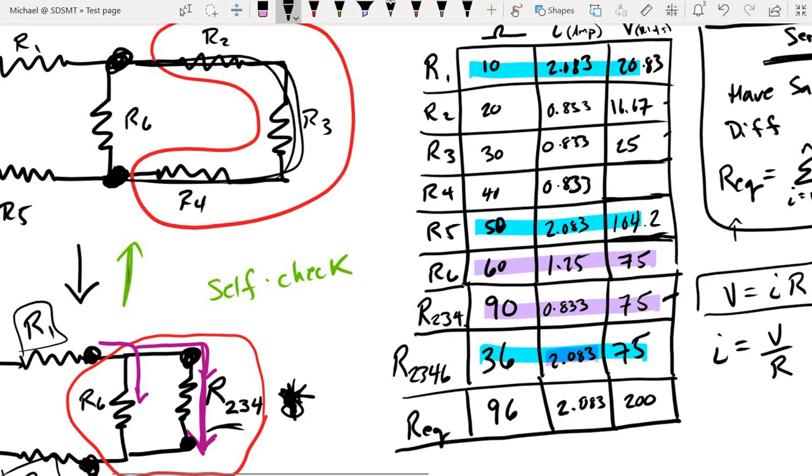And so that leaves us left with about 33.3 volts for the value of resistor 4. Well, do the numbers match up? Is that what we get when we take the value of current from resistor 4 times the resistance value of resistor 4? And yes, it does.